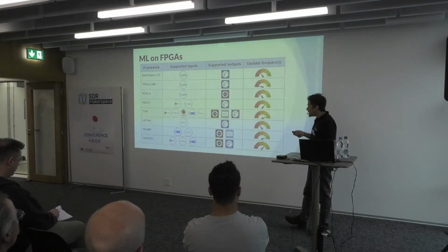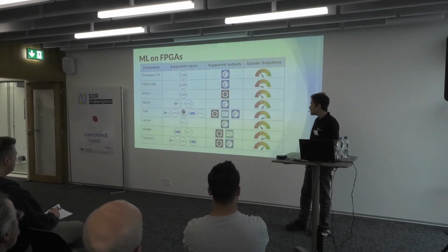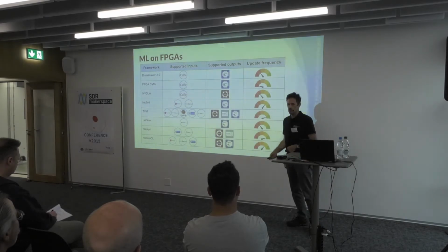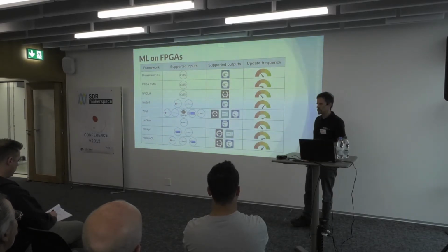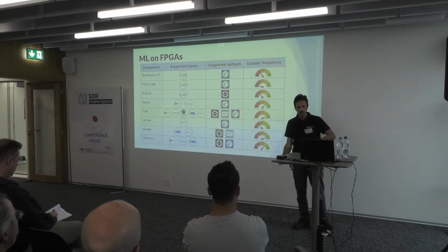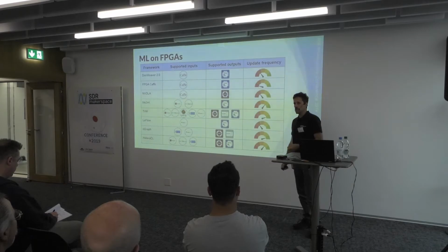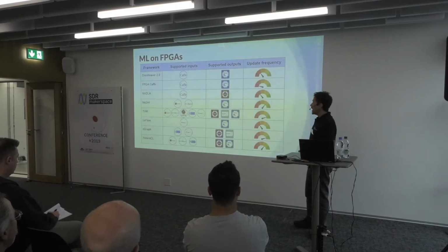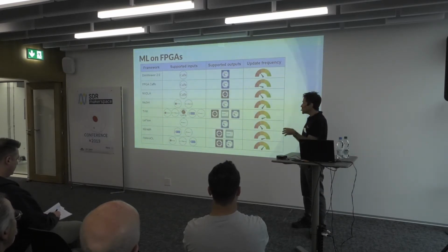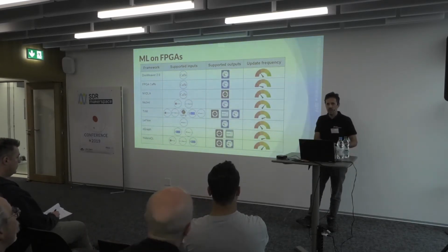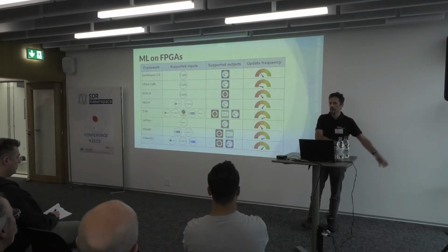Okay, but the idea is that yes, we have some open source tools to do the job. None of them is a push button solution. So none of them gives you the opportunity to take your model, push a button, and have the FPGA ready. They need some competence in dealing with tools, and it's a complex picture because probably the model is written in something like Python, but whoever works on the FPGA probably knows very well VHDL, Verilog, or something like that.